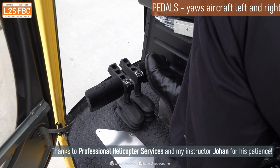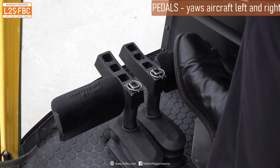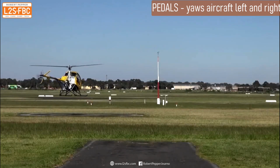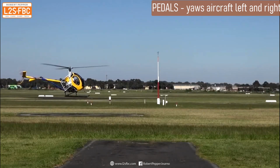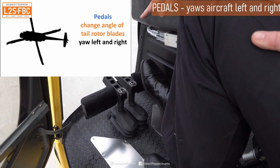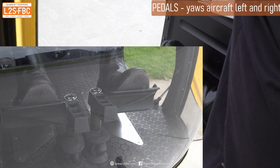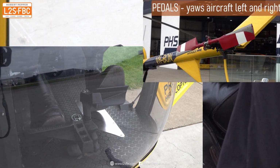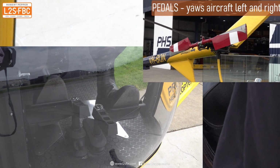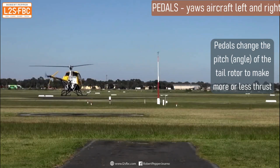Alright guys, so normally during flight, during hover and so on, you would always have two feet. For the purpose of this demonstration, I'll only use my right foot. So the pilot has got yaw control, which is really the nose moving either left or right by pressing either of the pedals. In this example, I'm going to push a right pedal back at the tail rotor, which we'll show you in a moment. The tail rotor will change pitch in such a way that it allows the nose to yaw to the right. I'll let go.